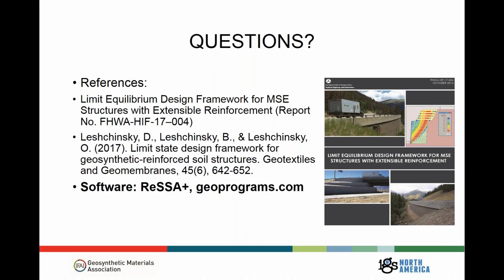Okay. Now, you spent a lot of time talking about pull-out and connection strengths. One of the questions that came in was with regard to how a contractor compacts the backfill behind the wall facing, and how do you account for settlement of the material and getting a step down where the reinforcement material comes off the facing and into the earth mass when that settles, a step-down effect coming off the back of the facing.